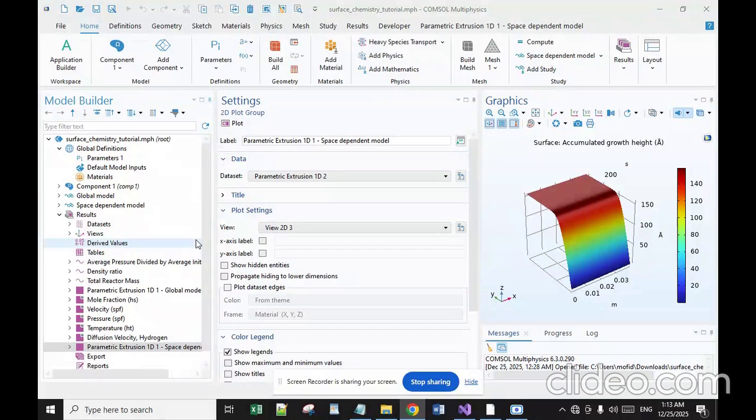and this simulation plots the integrated pressure in the reactor divided by the initial average pressure in the reactor. Once the problem reaches the steady state, the average pressure in the reactor has increased by a factor of 2. This is expected since every mole of silane is being replaced by 2 moles of hydrogen. The silane in the reactor is completely consumed after around 200 seconds.